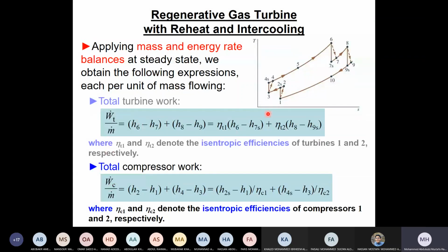So the data is, how do you present all of this cycle? Of course, first you have to set point 1. Point 1 is P1 and T1, normally atmospheric. So you want from me pressure P1 and T1. This has to be given in the problem. If not given, then we assume atmospheric conditions. So now we have fixed state 1.